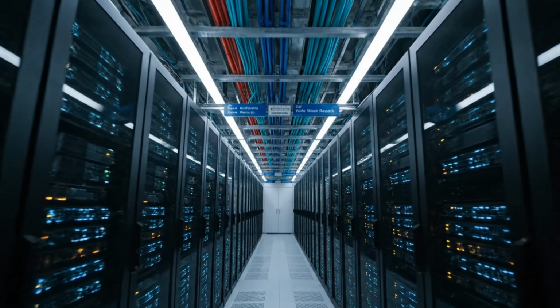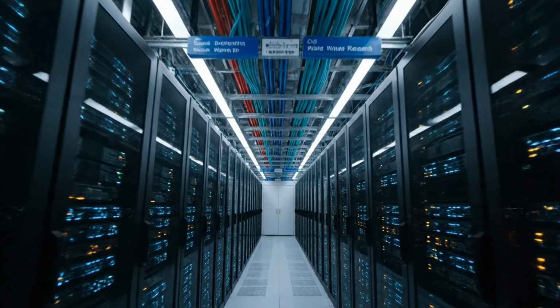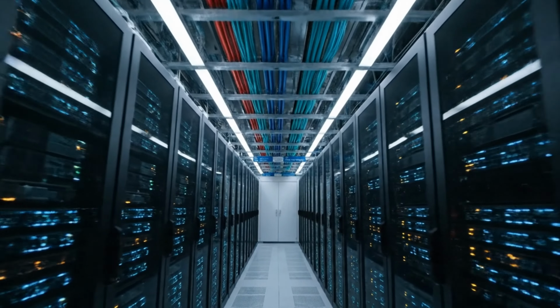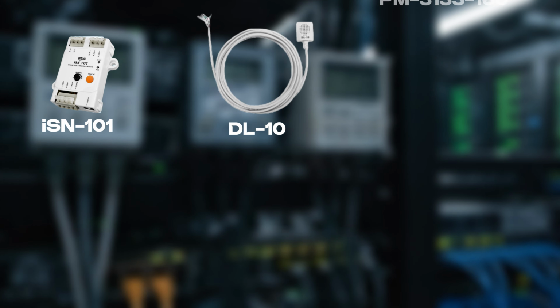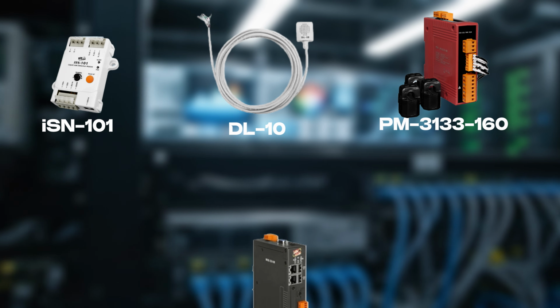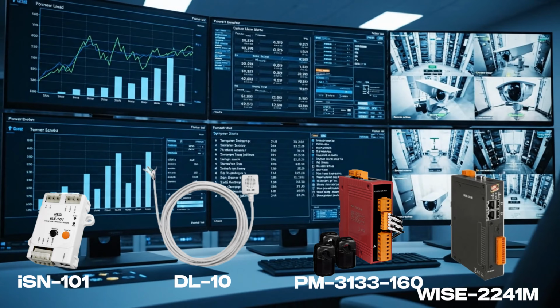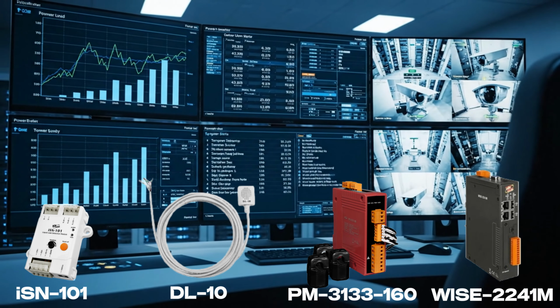Now, here's where the real engineering challenge comes in. Data centers never run on just one protocol. You walk into any facility and you'll see a mixture of serial leak detection devices, serial humidity sensors, serial power meters, Ethernet-based controllers, cloud-connected monitoring tools, and dashboards that expect everything to arrive over TCP. The environmental layer is still serial, but the supervisory layer is Ethernet. And the problem is that they have to work together.